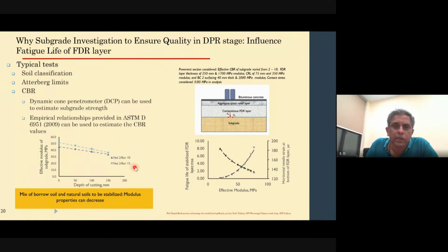Hence, that is what I'm going to have in my construction. Now, in my sampling, if I go ahead and use a vertical cut or a trench and collect the entire depth of that bituminous layer and use it for my mixed design, the quantity of bituminous material in my mixed design is going to be very different from what I end up having in the field when I'm constructing it. So when you are sampling for gradation analysis or for mixed design, the thickness of HMA that needs to be selected should not be 20 centimeters, but instead should only be 13.3 centimeters.